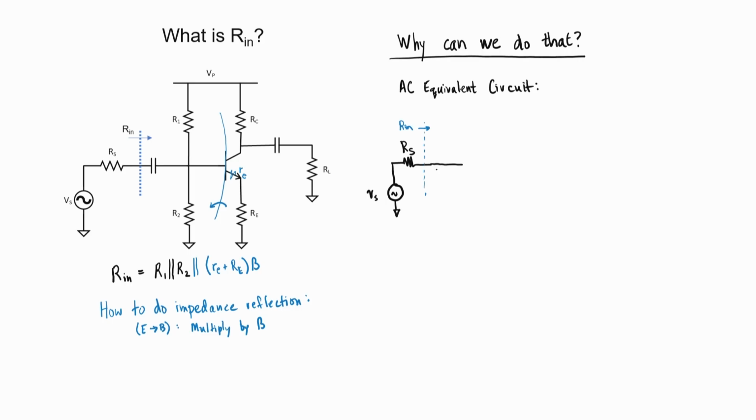Now from the perspective of the AC signal, resistor R1 leads to an AC ground up here at the top of the circuit. We then have resistor R2 leading to a real ground. We then have the base of our transistor, and I'm going to label it V sub B, and we're going to replace the transistor itself with a small signal model of the transistor. That is, over here we have a base, collector, and emitter, and I have the same 3 points over here.